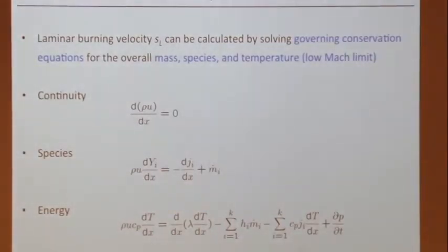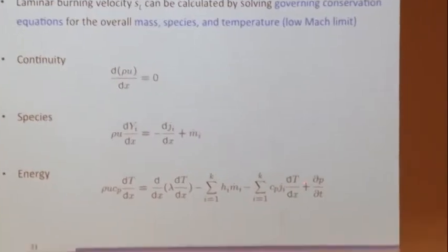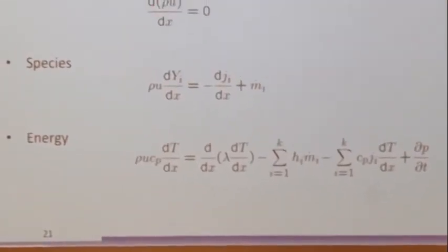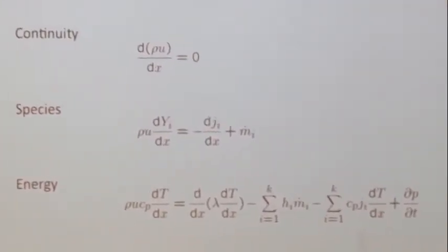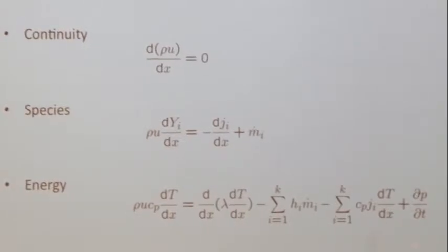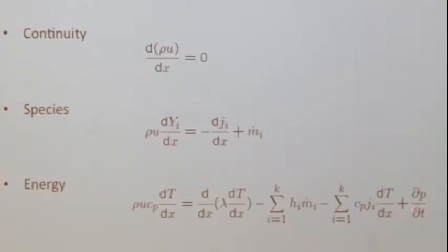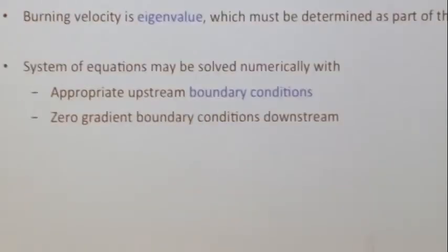There's one pressure left over in the momentum equation, that disappears here also. And then this is the thermodynamic or the background pressure that you would compute with the equation of state. And you see the pressure only remains here if you have a temporal pressure change, like in an internal combustion engine. So in a flat flame burner, this term here also goes away.